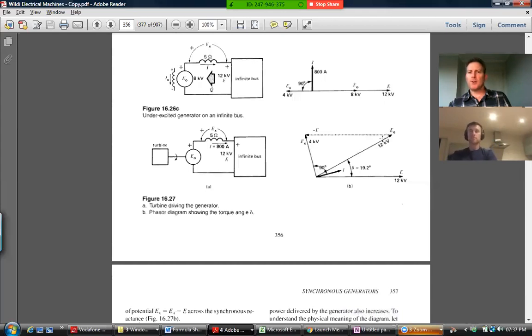what happens if you put the torque the other way. So if you have a turbine driving a generator, we could call that perhaps positive torque. What happens if you now actually try to resist that shaft? So you take the turbine away, throw the turbine away, you've got a spinning shaft there with these rotor and stator poles spinning together. If I try and grip the shaft, that's now actually going to become a motor. And I'm going to extract power out of it. My torque direction has changed.